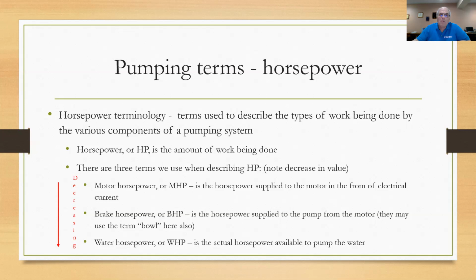So we started out big with motor horsepower. We lost some energy through inefficiencies. We went to brake horsepower. We lost more efficiency, and we brought it down to water horsepower.